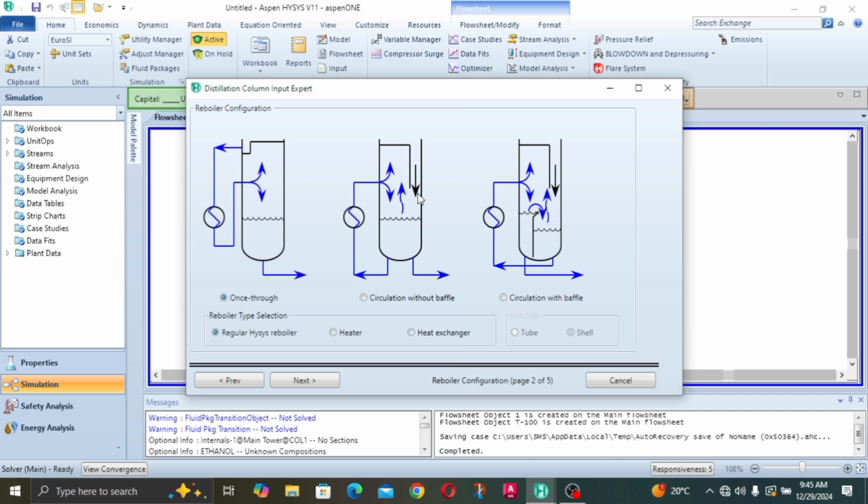So when the mixture hits the baffle before going down to the bottom of the column, it does a primary separation, making a turbulence in the mixture to separate the gas from the liquid, instead of the whole gas being trapped in the liquid and going down to the bottom to start the whole distillation process from scratch. So the baffle does a little separation, separating the gas from the liquid, and some of the gas goes to the top and some of the liquids with a little bit of vapor in them go to the bottom. So that's what it is.